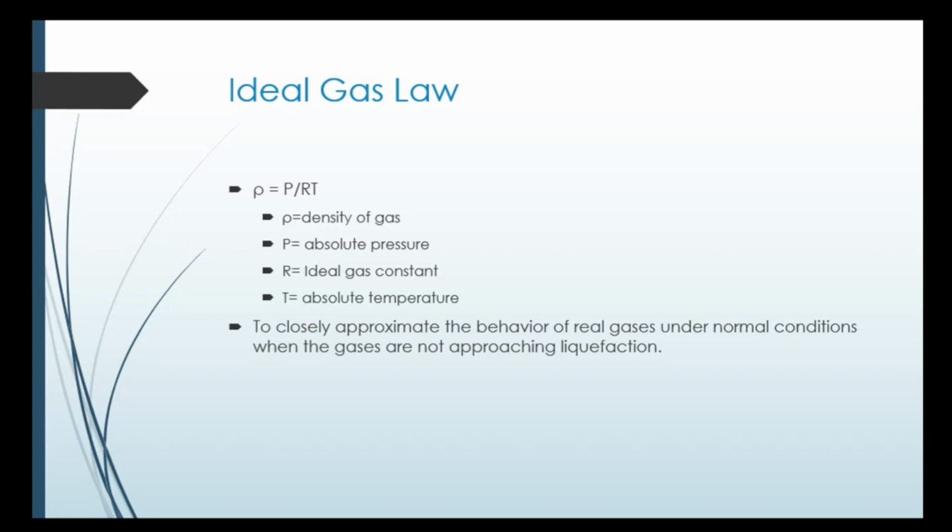Similarly, absolute pressure is from 0, in which you do not add the value of atmospheric pressure. The gauge which you use to measure pressure is indicating you gauge pressure because it is at 0 at atmospheric level, and atmosphere has pressure of 14.7 psi or 101.3 kilopascals, kilo Newton per meter square. So that in gauges you have nullified that 101.3 kilopascals.